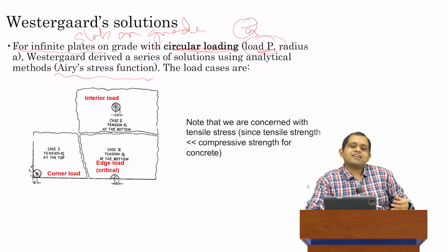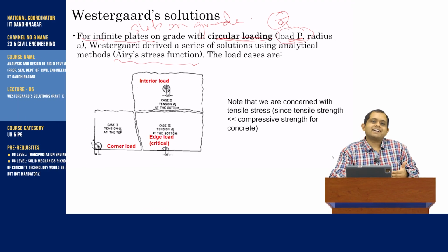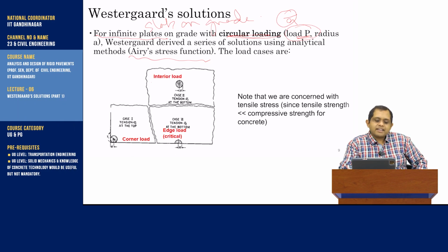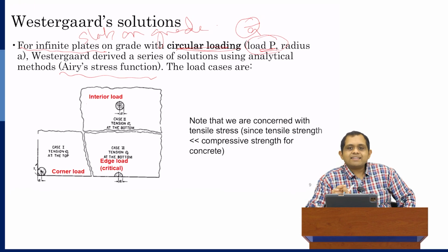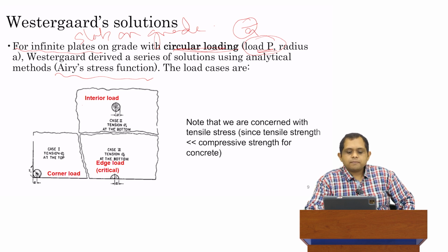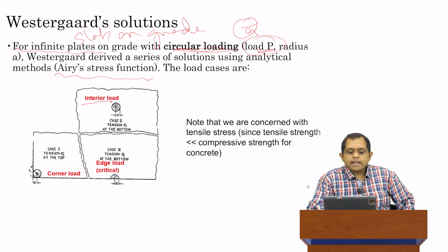So it's not that we start from the problem and then systematically derive the solution. In practice with the Airy stress function, what happens is that we look up a series of solutions which mathematicians have derived and try to find the best solution which suits our case. So what are the cases that we're particularly looking for? Westergaard solved or provided analytical solutions to the equation for three particular loading cases: interior loading, edge loading and corner loading.